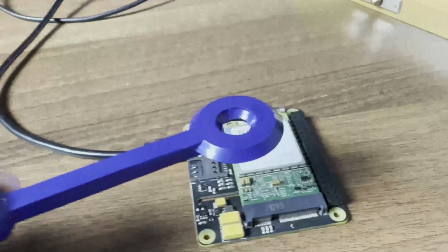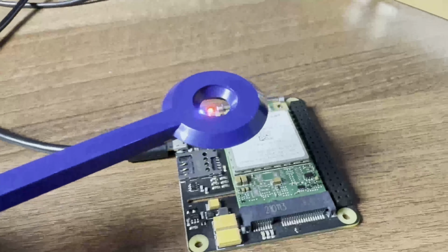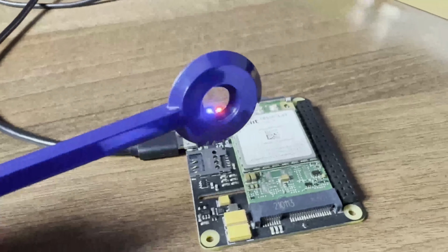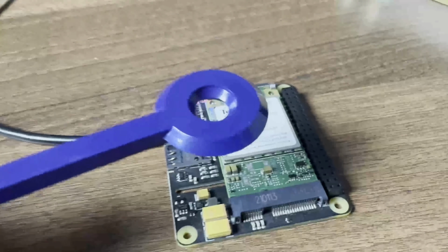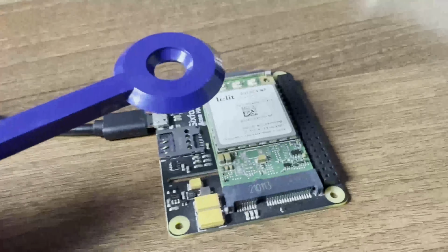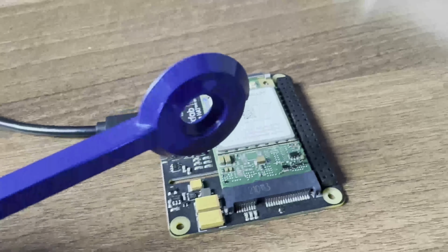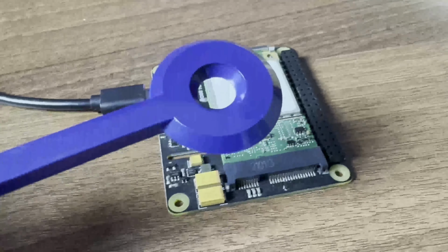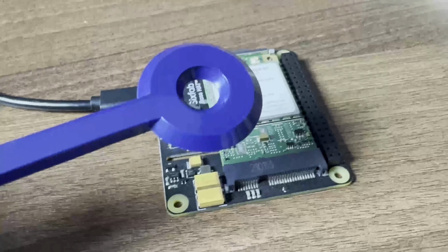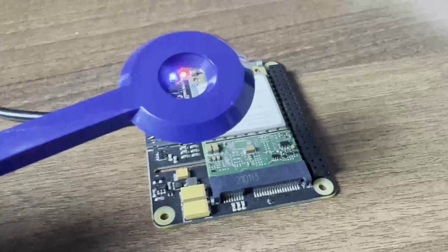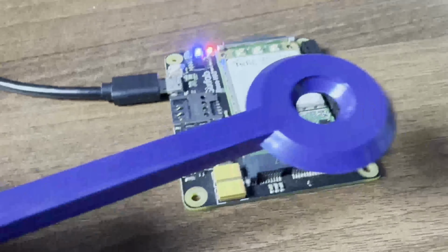And just when we're using magnetic field probes, it really is important as well in what orientation they are, because they are polarization sensitive. Which means that as the electromagnetic wave originates from the printed circuit board, it's going to have either magnetic or electric field dominating in the near field. So you want to try both polarizations so that you get an accurate picture.